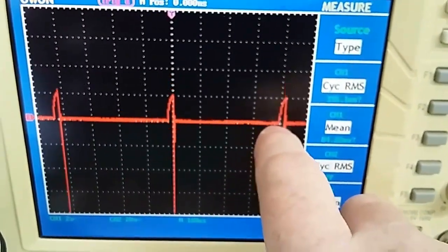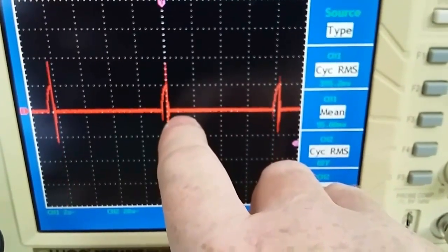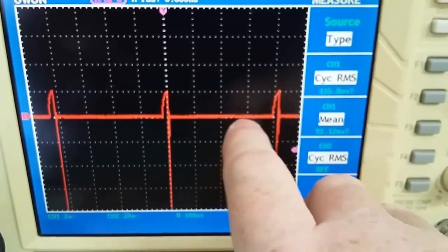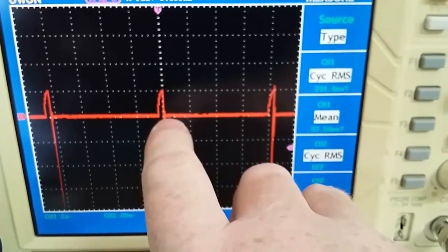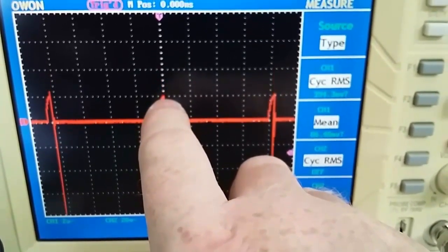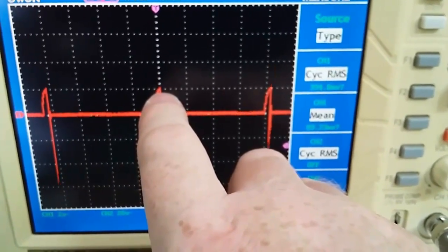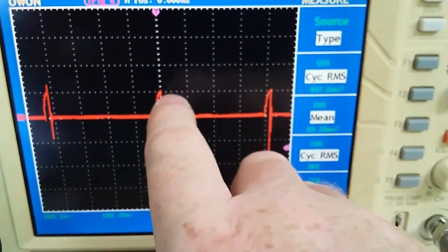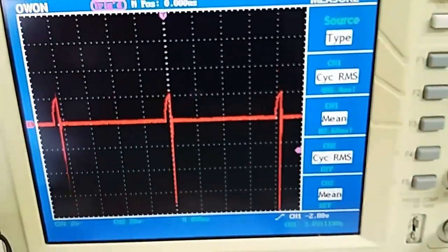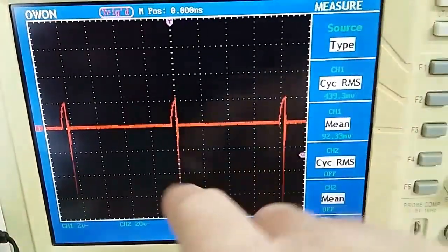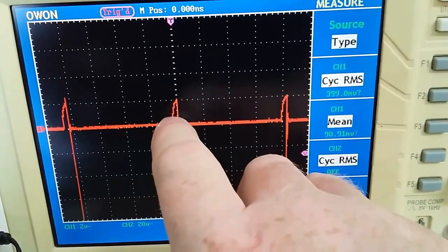Every part of this line when it's zero is a time that the secondary output coil is not being supported by a current in the system. So if our input was on for longer, then our secondary coil would carry current for longer. And the reason it would carry current for longer is because we are supporting that current from our input.